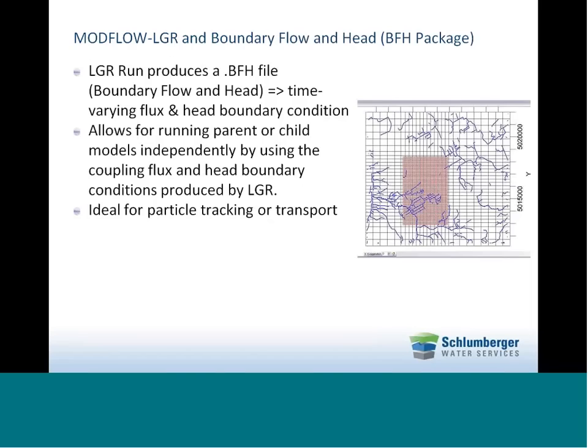So following up, as I mentioned, an LGR run produces a .bfh file, which is a new package for Modflow LGR called boundary flow and head. Essentially, it's a time-varying flux and head boundary condition at the interface between the parent and the child grid. This allows you to run either model independently using this as an input for the boundary conditions. And this is ideal if you want to do particle tracking or contaminant transport.